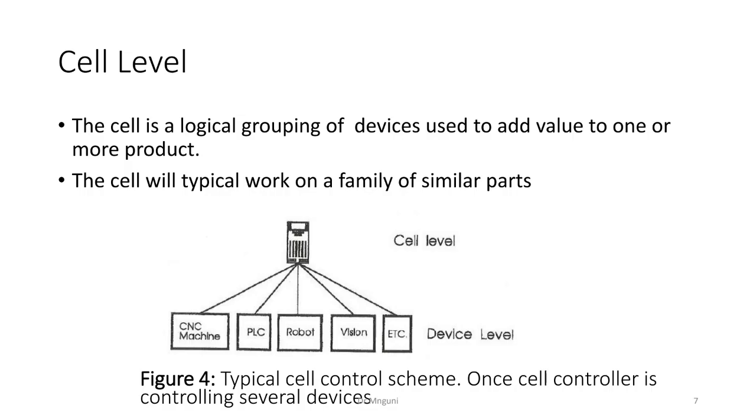Going back now technically to the cell, all right? The purpose of the cell, which we also refer to as a controller, is to integrate all these various devices into a cooperative work cell. The cell controller must then be able to communicate with each device. Even if devices are not able to communicate with each other, they must be able to communicate with the cell controller. So the general workers, even if they don't have to speak to each other, must be able to speak to the foreman individually, okay?